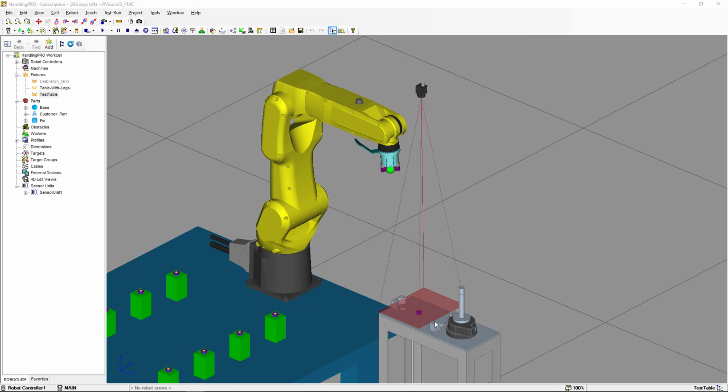So we know already that we have two constraints. One is going to be the standoff distance, that we know that we cannot make it smaller, otherwise the robot is going to hit the camera. And the other constraint is going to be the size of the field of view, that has to be small enough to just look at the location of the part.